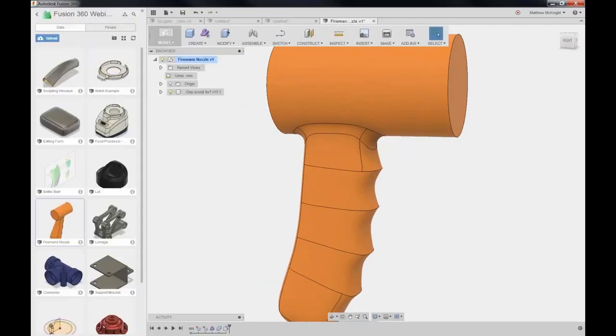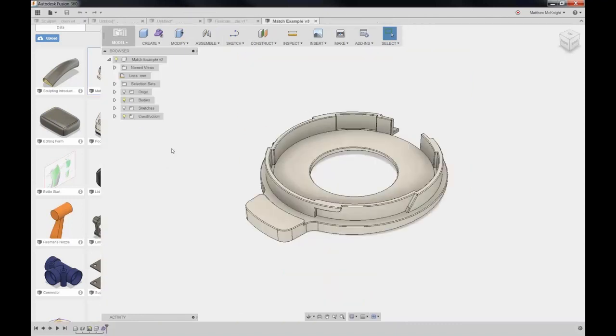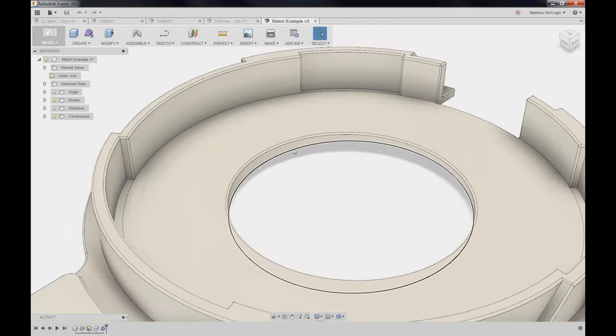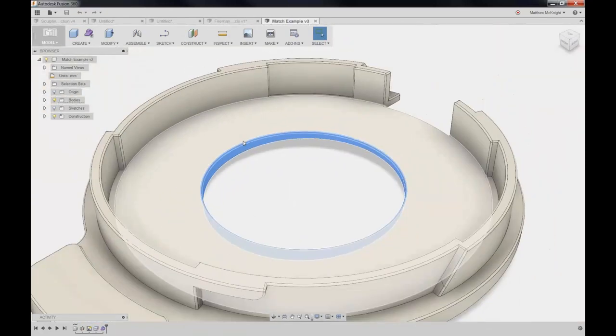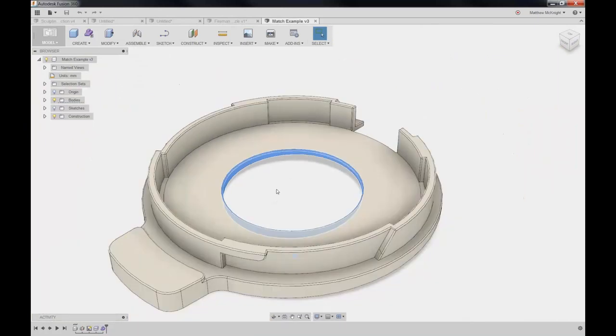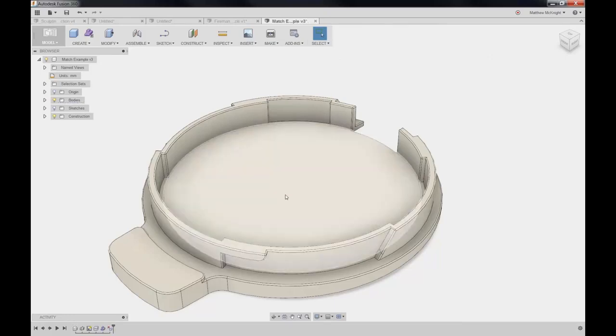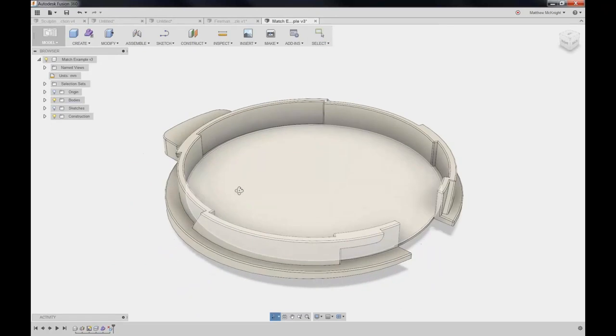Now quickly, just finishing off something that I talked about a little bit earlier, and that is the delete command. The delete command inside of Fusion 360 is extremely powerful, better than I've seen any other CAD system handle, especially imported geometry. So in this case, if we've imported a part, this is just a simple maybe plastic part, we want to delete out the hole in the center of it. I just highlight the two surfaces, hit the delete key, and it removes that geometry from our part.